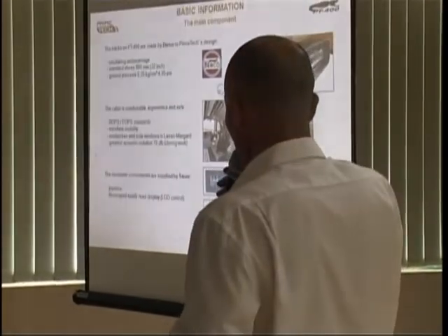Because we need to make the surface stable, which means it should change as little as possible. Stable. Okay? So, to make a surface stable with minimal changes, you have to have the size of the material inside the road similar. Because if you have the size different, yesterday I saw some roads with different size rocks. So if you have different size rocks and you try to compact them, you cannot. You can try, put a roller, you can do what you want, but it's very difficult to compact.